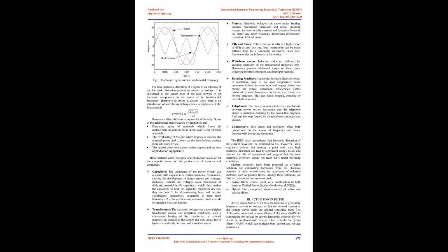In the three-phase electric grid, the principal harmonic components are the harmonics of ranges 6h plus or minus 1. Transformer energizing current, arc furnaces, rectifiers and numerous different loads will produce harmonics in the utility lines. Most utilities limit the reasonable harmonic current levels to the values shown in IEEE 519. Fig 1. Harmonic signal and its fundamental frequency.